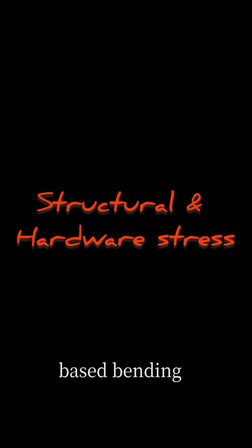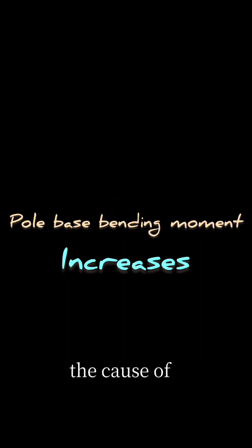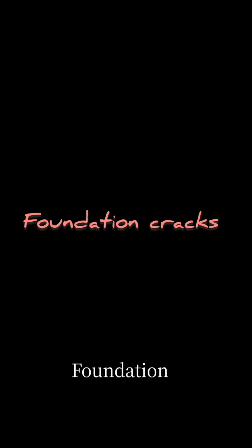The second stage is structural and hardware stress. Pole-base bending moment increases. What is the cause of this? Lateral force acts due to the tilt. As the pole is tilted, there is a lateral force acting on it. What is the effect of that? Foundation cracks or the pole breaks. The foundation of the pole is going to break.